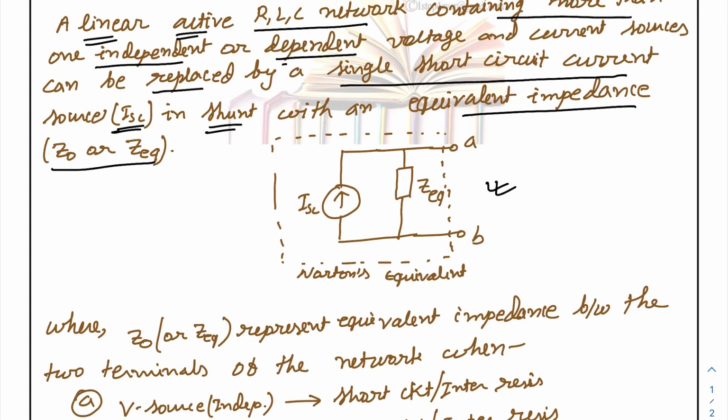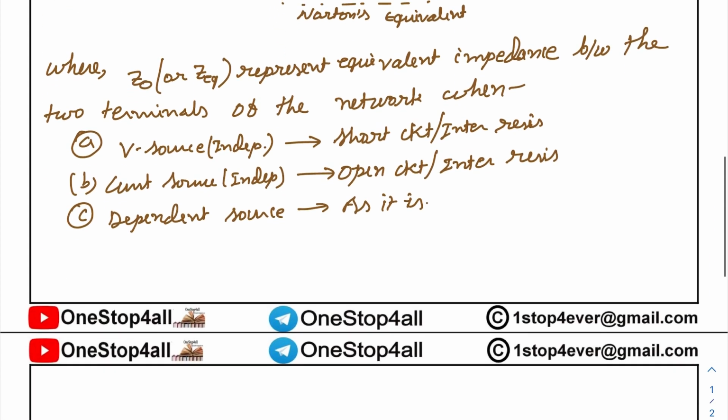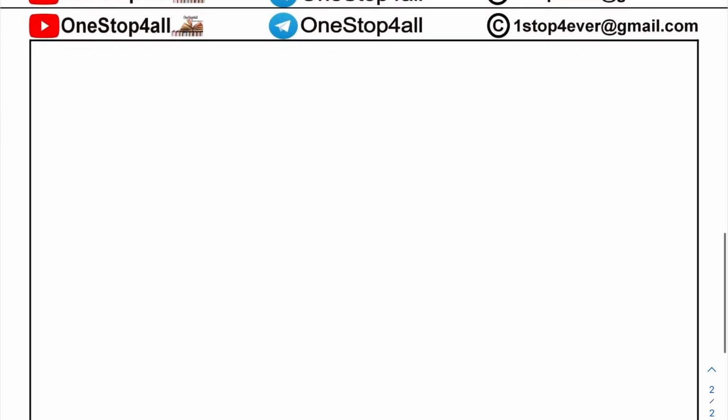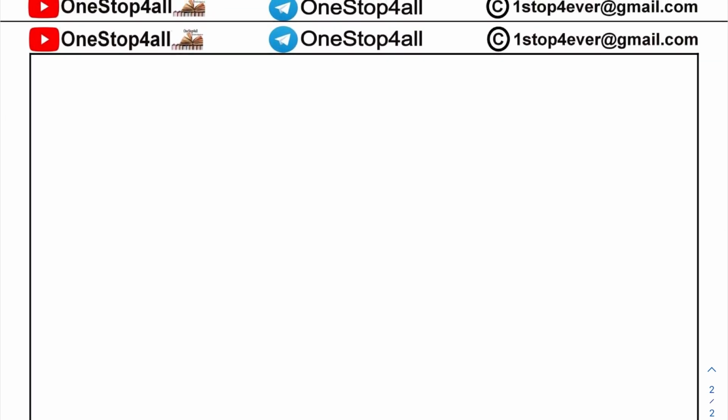नॉर्टन के थ्योरम थे. ठीक है, न्यूमेरिकल देखेंगे और इजीली हम लोग अंडरस्टैंड करेंगे कैसे हम लोग नॉर्टन इक्विवेलेंट कैलकुलेट करते हैं. ठीक है, और यहाँ पर कुछ पॉइंट्स है, जैसे नॉर्टन इम्पीडेंस क्या होता है, इम्पीडेंस, और रेजिस्टेंस किस केस में हो जाएगा, जब आपका डीसी सर्किट हो, सब कुछ डीसी होगा तो उसमें सिर्फ रियल पार्ट ही होता है, दैट इज द ओनली रेजिस्टेंस विल बी देयर. इफ देयर इज एसी देन इम्पीडेंस कंसेप्ट विल कम इनटू पिक्चर.